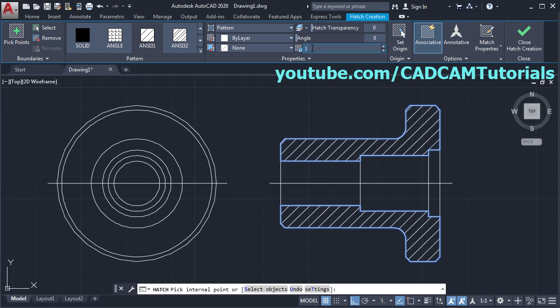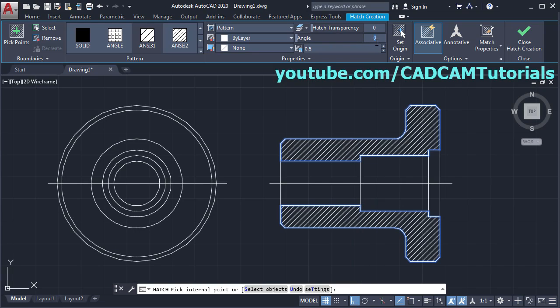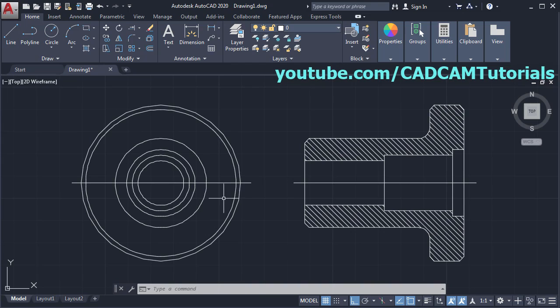Then reduce the scale. We'll choose 0.5. Enter. Then here the hatch direction is opposite. For that, we will change the angle to 90. Press enter and click on close hatch creation. So this hatch is also created.